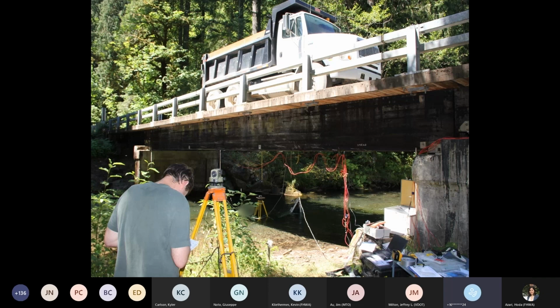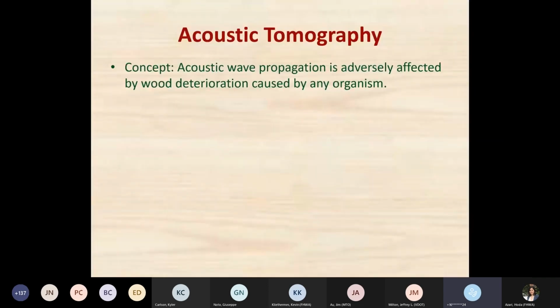And so we attached a whole bunch of fancy transducers to measure dynamic loads as the vehicle crossed. But in addition to that, we set up an optical survey and we put rulers hanging down from each girder. So that's something an inspector could do quite easily at the county level without too much cost, and measure the deflections of a bridge and get more of the system response. Is one girder not performing well compared to the others? Next slide.